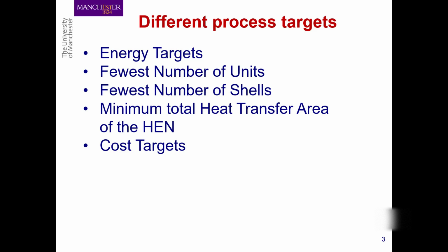We have gone for this because counting the number of units will not give an accurate result, as the shells will, because a heat exchanger can be made up of many shells in comparison to one shell, and this happens when we are dealing with a low FT parameter. If you compare the cost of a heat exchanger with a single shell and one with multiple shells, a heat exchanger with a double shell will cost almost double in comparison to a single shell.